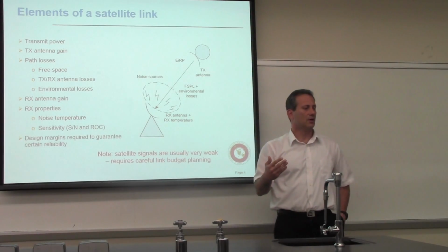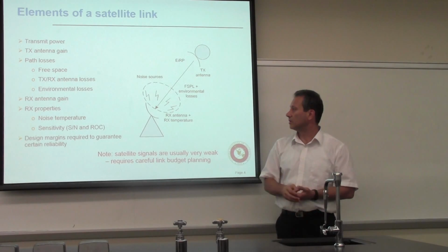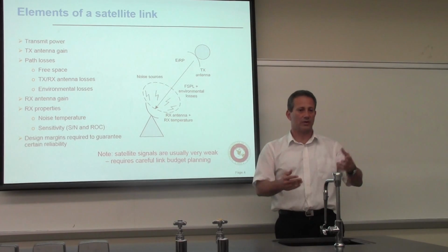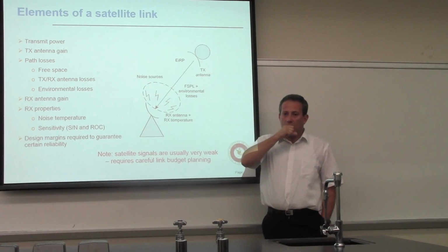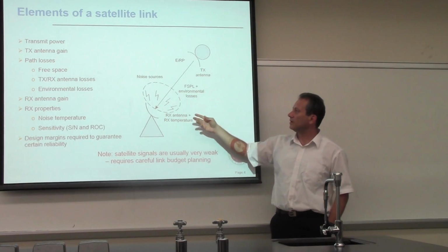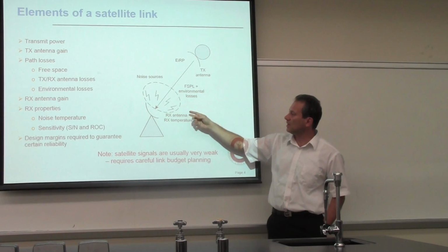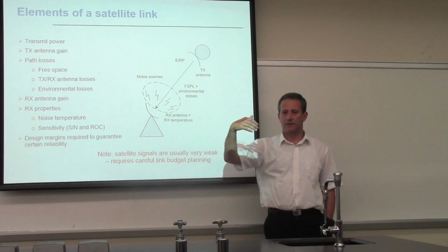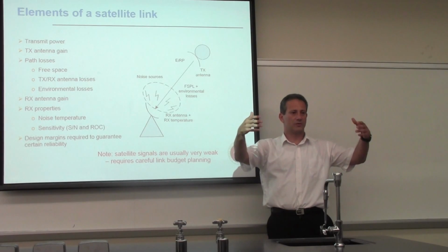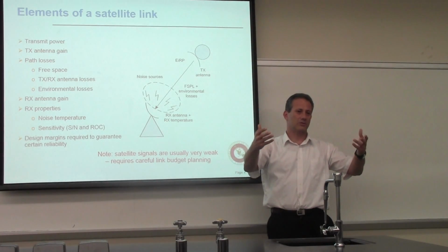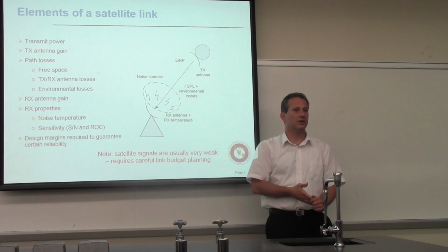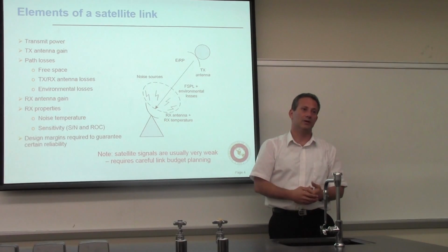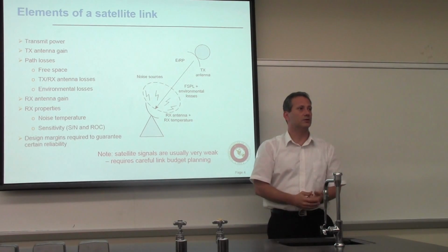And predominantly here, you have your thermal noise, the noise of a given temperature. And here we have asymmetry of the two links as well. However, we kind of a little bit luck out here. In what sense? Because the noise that we're talking about is the noise from what is called black body radiation. If you point your antenna into something that is having a certain temperature, it will have some noise coming in, because everything that is not at zero temperature radiates some energy.